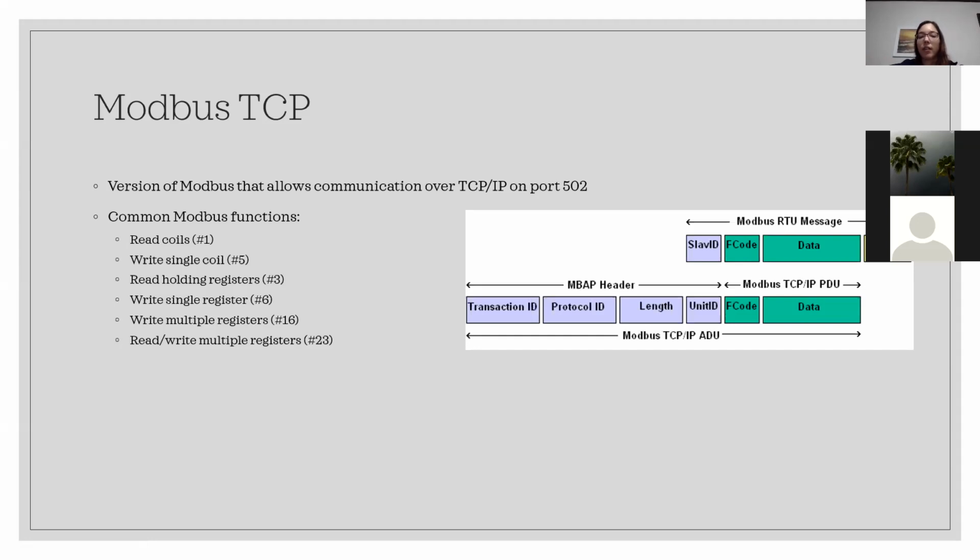Well, if you have an authentication mechanism, suddenly you're adding either a lot more length to a packet or multiple more packets to the back-and-forth sequence in order to authenticate. That slows down the communication substantially, and you can no longer get that information as quickly. You can't get that accurate 15 millisecond state update from your sensor.